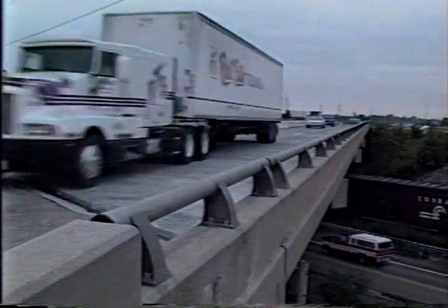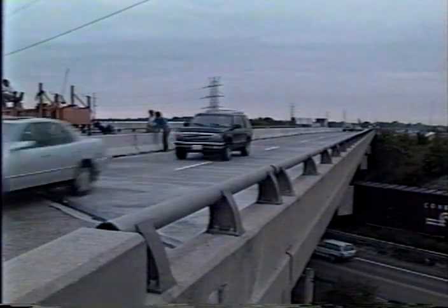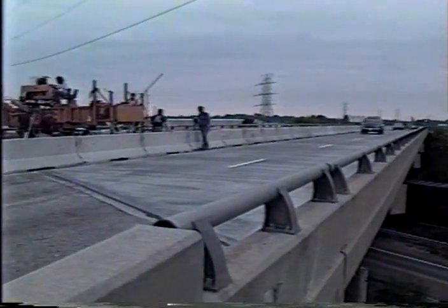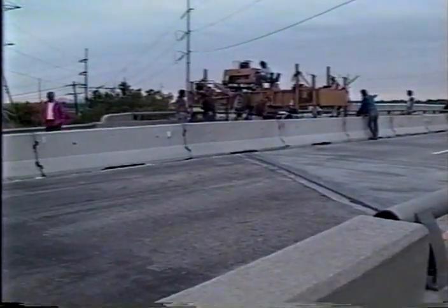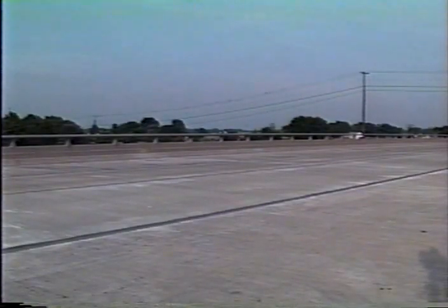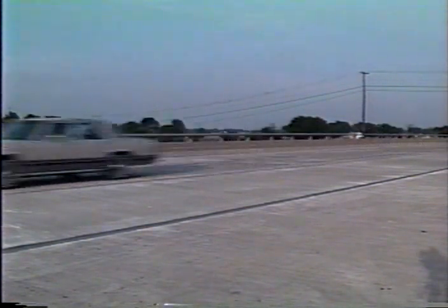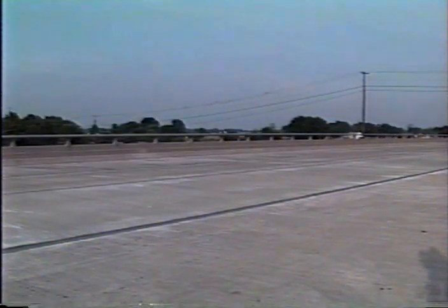Advancements have also been made in the rehabilitation of concrete structures. Like pavements, structures can exhibit many different types of distresses. One of the more common problems with concrete structures is the deterioration of bridge decks, consisting typically of cracking and spalling. This deterioration is generally attributed to the corrosion of reinforcing steel due to the infiltration of chlorides into the deck structure. An overlay of the bridge deck will restore the riding surface while making it largely impermeable to the penetration of contaminants.